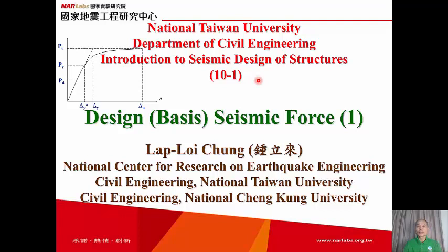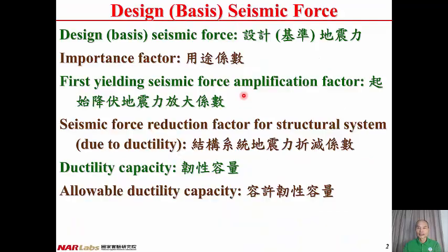This is lecture 10-1, Design Basis Seismic Force 1. Seismic force is used for the design of structures, and design basis seismic force is the seismic force corresponding to the design basis earthquake level. Here is some terminology. Design basis seismic force is the seismic force for the design of a structure at the design basis earthquake level.